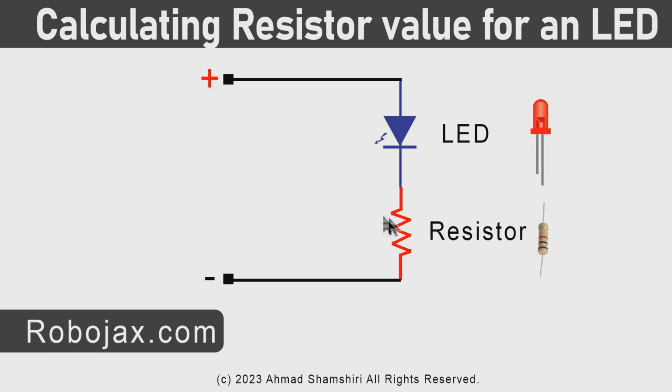But we can also put a resistor like that. The only important thing is it should be on the path. It doesn't matter here or there, in cathode or anode. Still, this will divide the voltage and it will have 3 volts, and 2 volts will be on the LED, and the LED will turn on if we connect it like this.